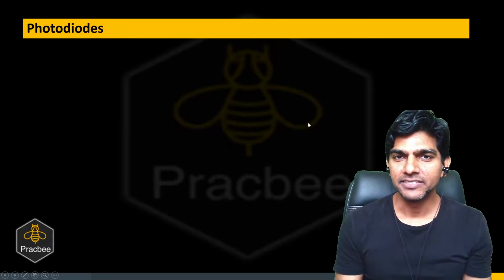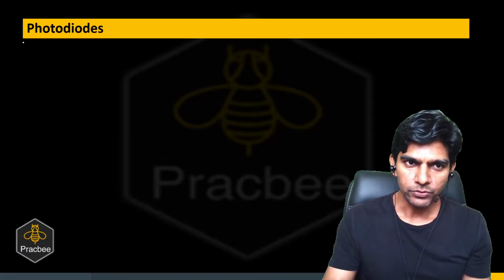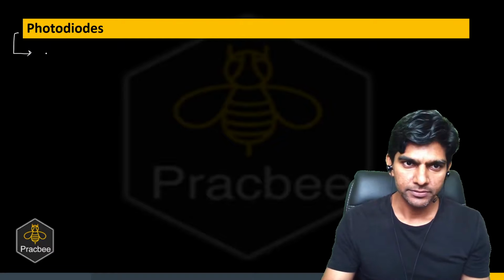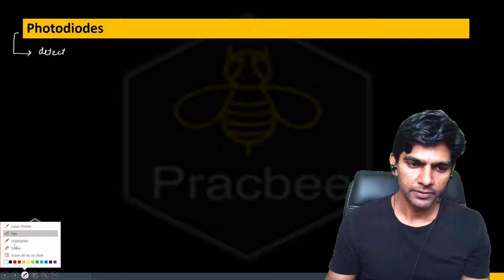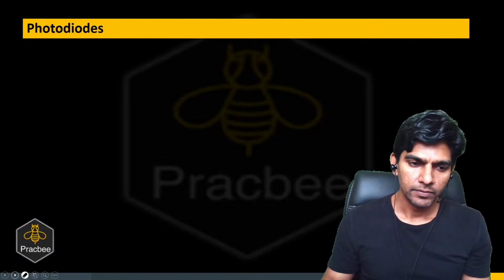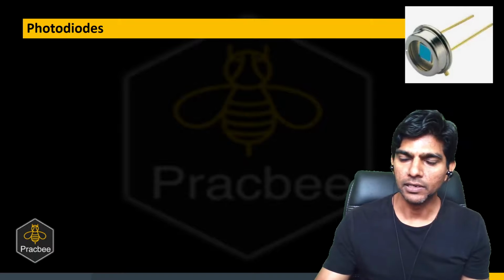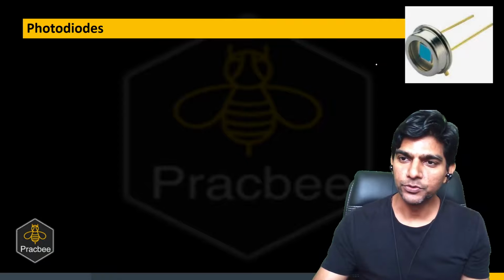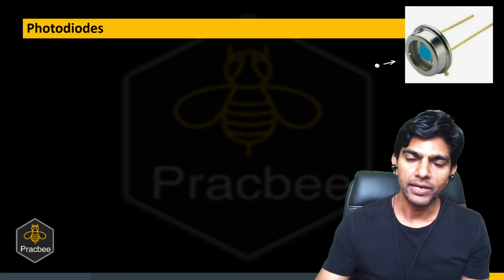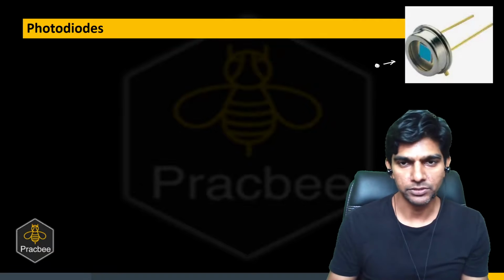So now let us see another special purpose diode, and that is a photodiode. We use a photodiode to detect photons. If I show you how it looks, there is a glass window, and this glass window is provided so that the photons can pass through it, and they get absorbed at the depletion region.